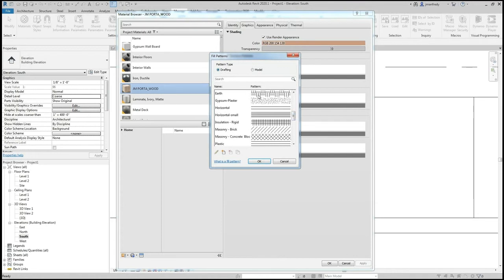They work based on the current scale of the drawing, but they change. So if the scale went from an eighth or a quarter to an inch and a half, these will subsequently change scale because of the scale change. They will look different per scale. Model means that they measure exactly the size, no matter what scale you're at. So if something is 2 inches wide, it'll stay 2 inches wide.